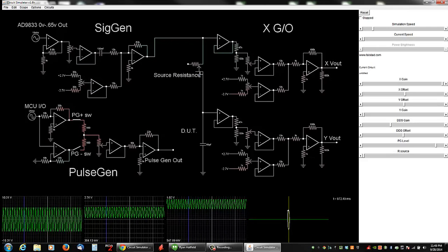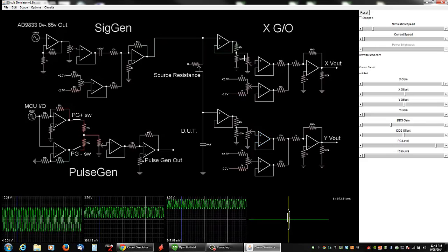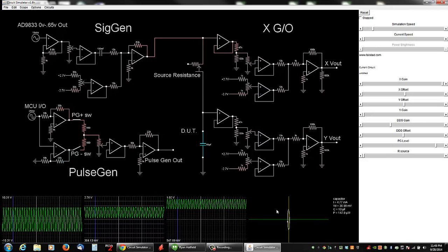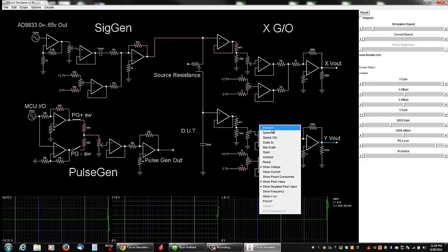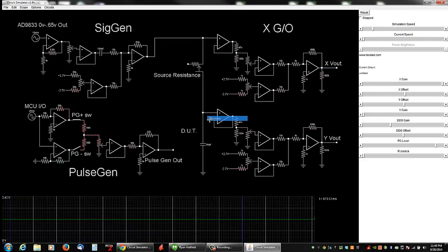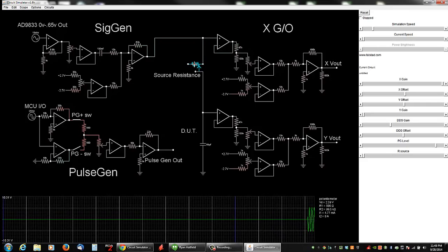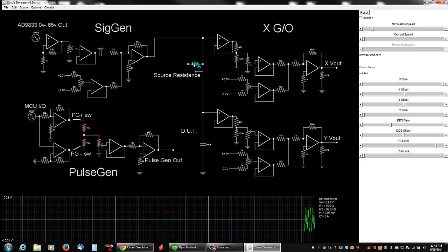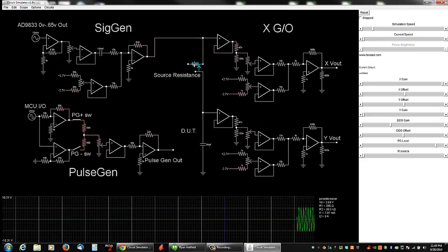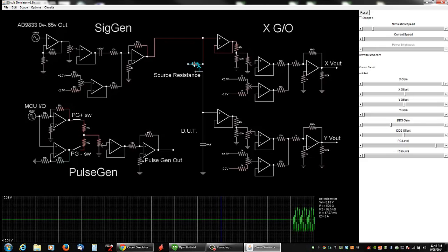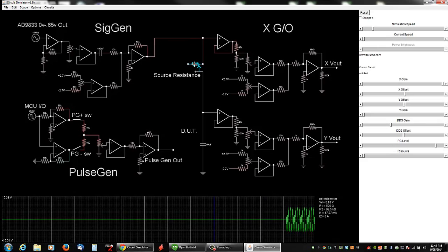Digital pot, digital pot, digital pot. 4 op amps per section. You know what? Let's go ahead and throw in the pulse generator for the hell of it. And for the source resistance, there's going to be an 8-channel analog multiplexing switch selecting between 8 different resistors. Only because I can't find a digital pot that'll handle the current. But I can find digital switches that'll handle the current.